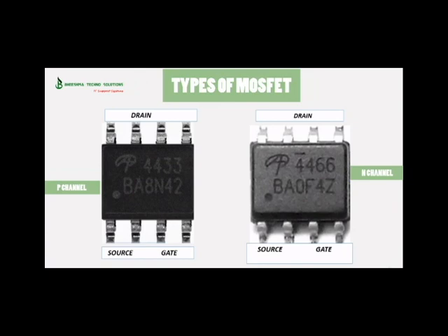It should show between 300 ohms to 550 ohms. Check again in the reverse direction and it should show high resistance, that is no reading on the multimeter.